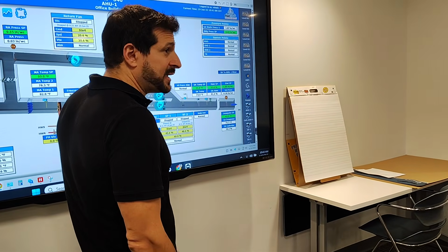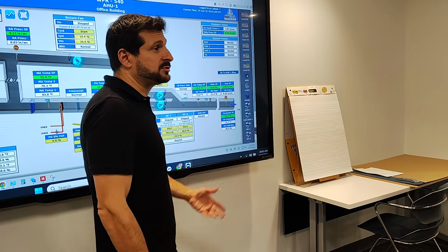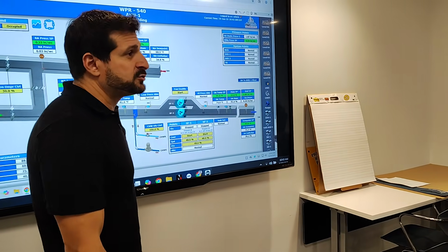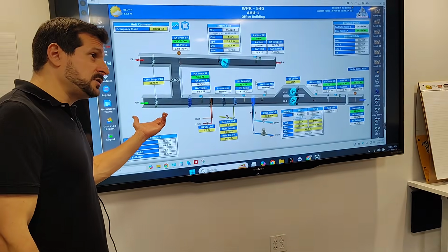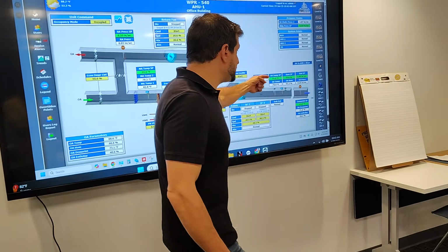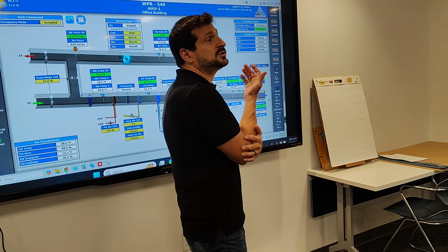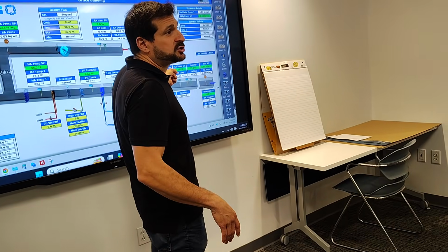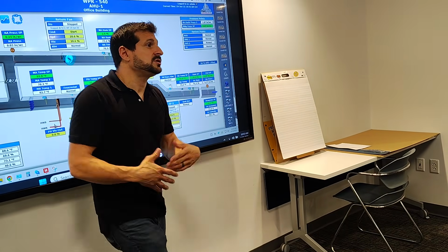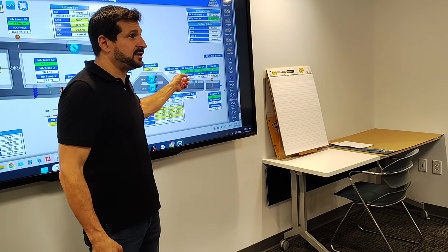It does seem to be trying, because the chilled water valve is 100% open, but we already know the chilled water temperature is 60 degrees, so you don't have chilled water to make the space colder. So you'd have to get your chilled water working first. That'll give you cold water, and if this thing actually maintains 55, then your floor will go to that temperature. Now, if it turns out you have a problem on the floor and they need it to be warmer, you'd have some limited functionality changing this. You can't change the way the VAVs work, but you have some limited functionality adjusting this.